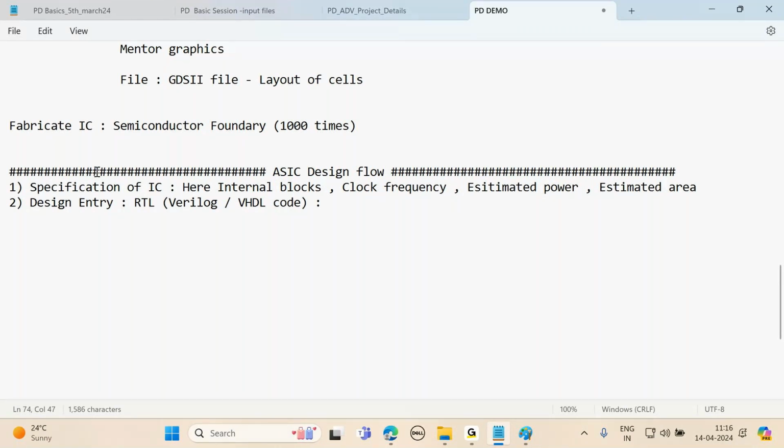Now, why have they introduced this programming as one of the parts in the flow? They could directly write the circuit. Why have they introduced programming languages like Verilog or VHDL? Hardware programming languages, hardware description languages. Why do we have to describe the hardware using these languages? For simulation. We do simulation because we are describing through these languages, to verify whether whatever we have defined using this language is proper or not.